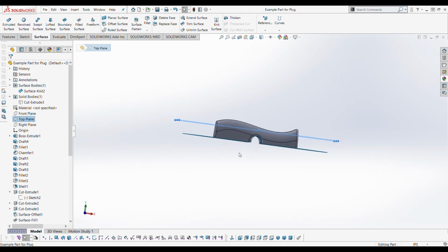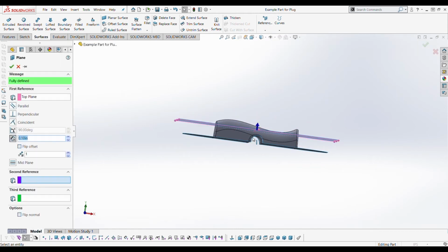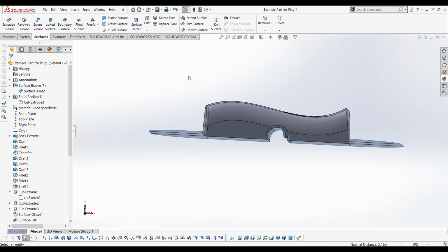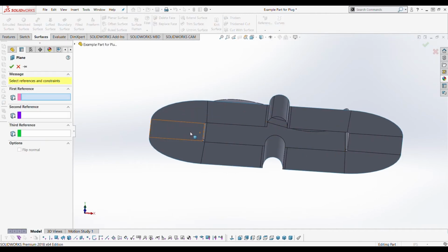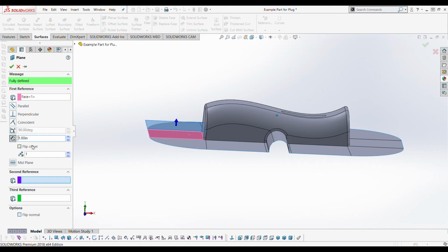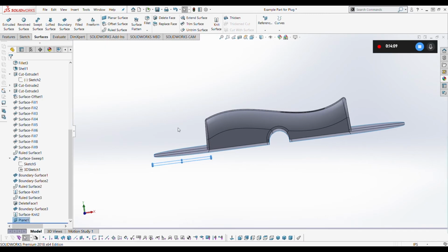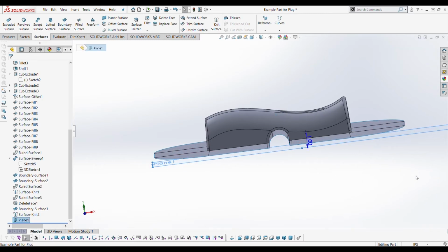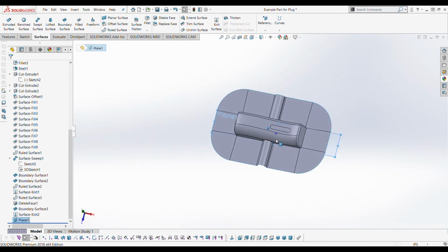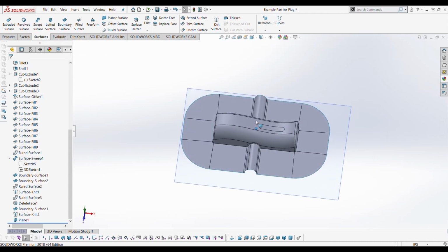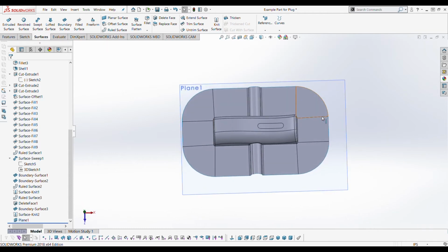So I would like to put 1 inch below our bottom surface. Let's add ourselves a flange plane, and let's flip that and change it to a direction. Oops, close back out of that. Let's go off of here and say 1 inch offset downwards will be the base plane for our part. And just extend this plane out a little bit. So we now have a pretty simple way to convert this into a solid.